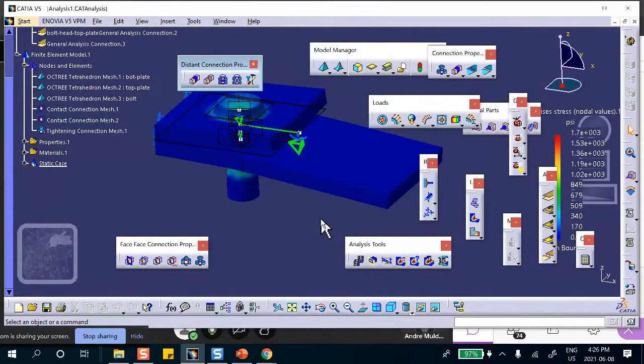That's very good because I am pretending that the bolt shaft does not establish contact and go through those holes. If in doubt, and if there is such a close, tight fit, then you better put contact between those two. But pretend, just for a second, that the diameter of that shaft was maybe a third of the diameter of the hole. You know it's not going to establish contact. Well, actually, you can have a thread there if it's one third of that. The short answer to your question is yes.